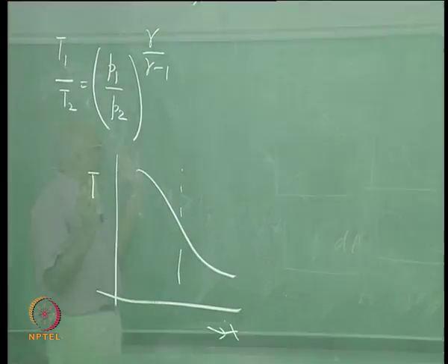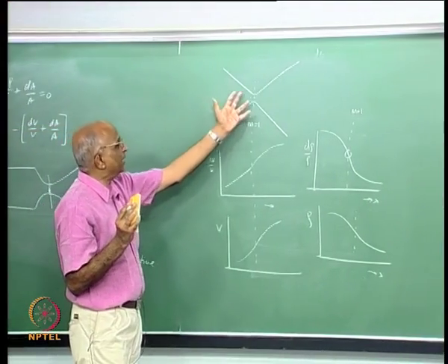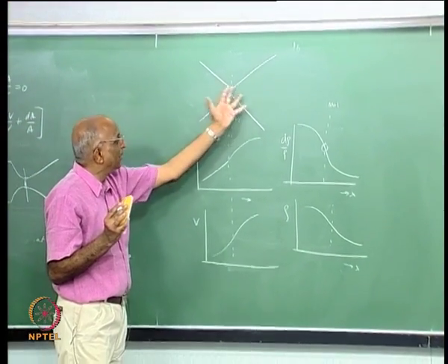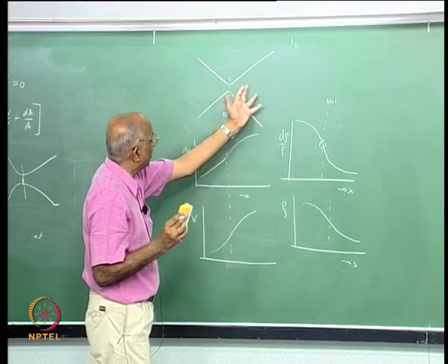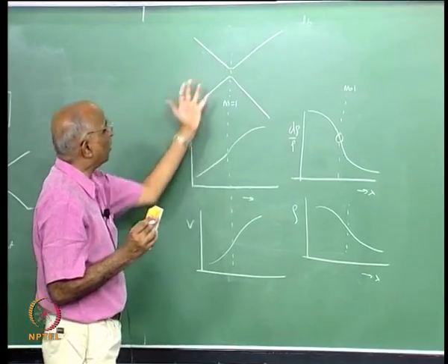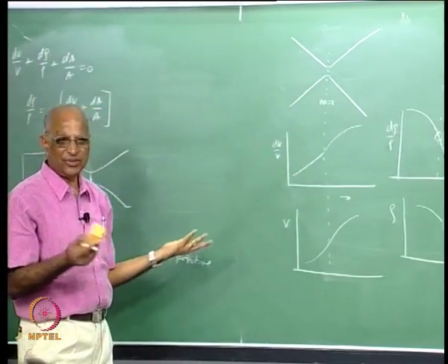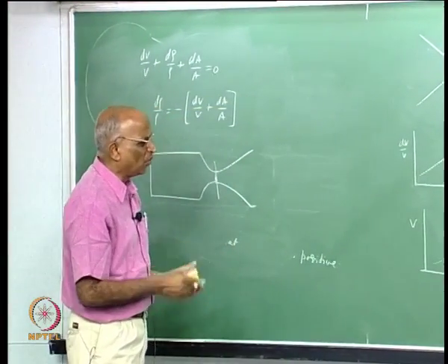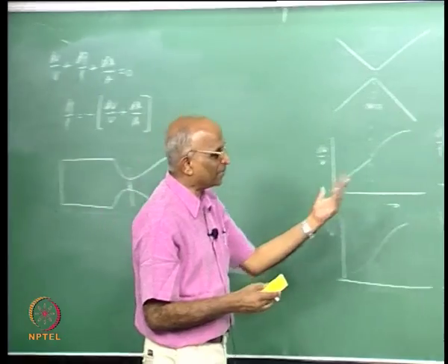See, all what we are telling is the pressure decreases in a nozzle monotonically, the density decreases in a nozzle with rapid change in density happening at the throat, and the velocity increases. This is all what we have said, and this is something which all of us know. Now let us put some other parameters.